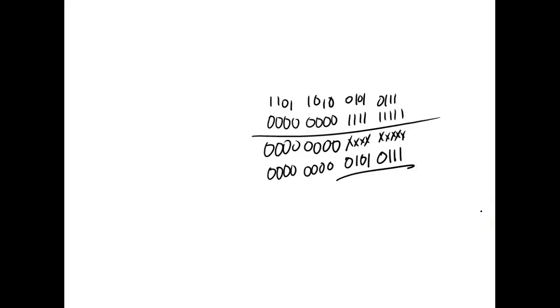So you're trying to look at it as the number 15 or the number 255. But when we're doing mask, we're doing them on a binary level, and it is bitwise logic. That means we're doing 2 bits at a time. Bit 0 of one operand is being ANDed with bit 0 of the mask. And that's why when you put those ANDs and ORs, if you ever notice, it says bitwise.